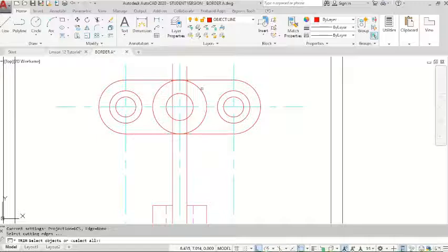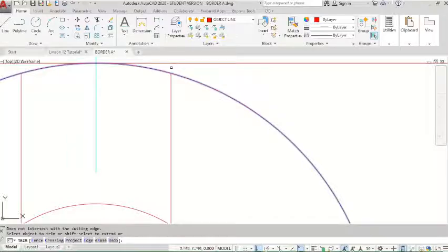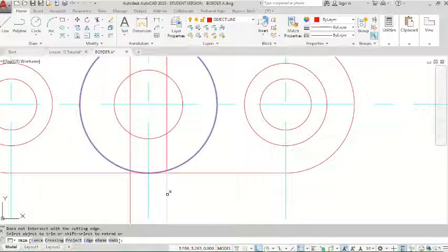I'm going to pick a circle. You guys don't have to do this step on yours because you're using the newer version, but you will now have to trim these off, and make sure when you're trimming them that it's not cutting it off at the top line, that it's actually getting the little bit between the circle and the part. And I want the middle of it gone.